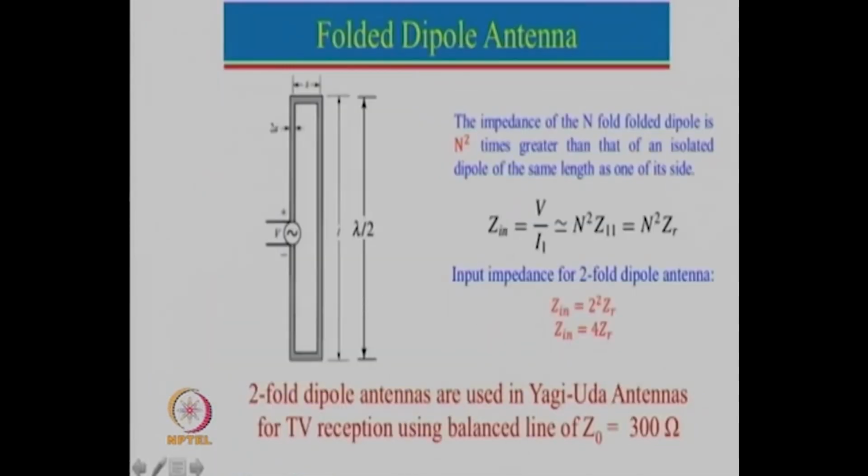So over here, we should take this particular length as 0.48 lambda, which will be L plus D. So for that, the impedance will then be approximately 68 ohm.